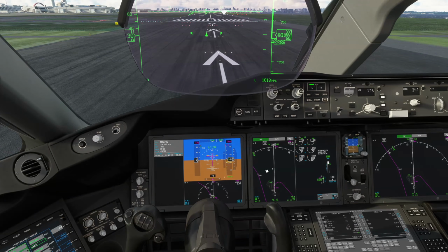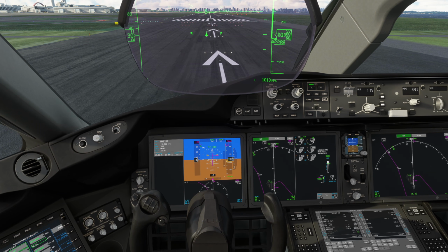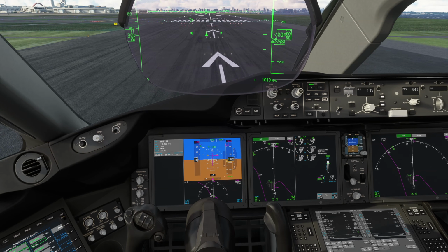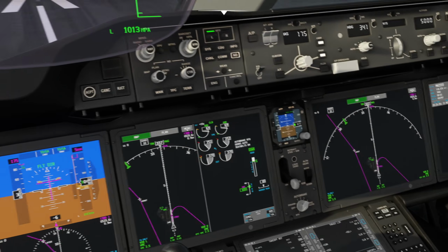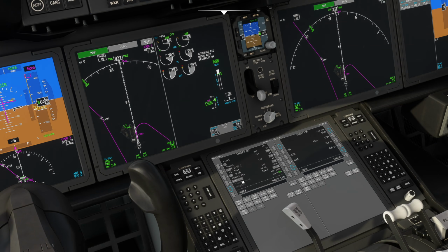Okay, so brakes released. Aircraft is now rolling. Bit of forward power. Forward on the yoke. 20 TPR. Oh, hold on. I can see there's a problem here. I can see that the airplane, because I did just reset this from last one, see it says climb thrust. It's not got the correct thrust setting in there.